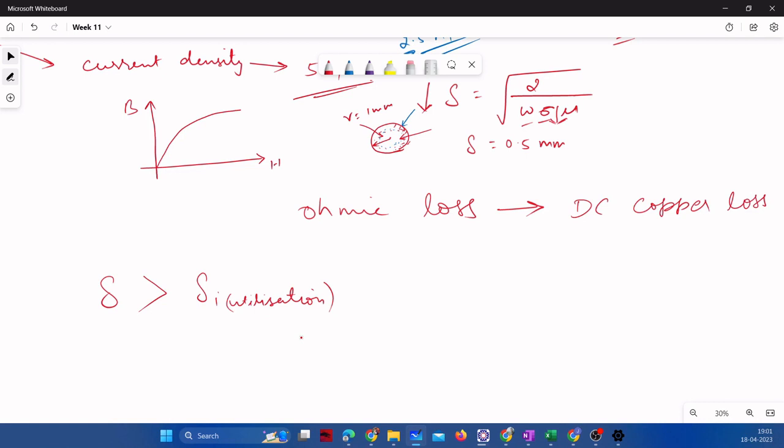So in that way, whatever AWG comes, 12 or 14, we need not bother about skin depth, because it is a DC inductor. But in a transformer, this is not the case. There we have to use this Litz wire, but here we need not. I think so.